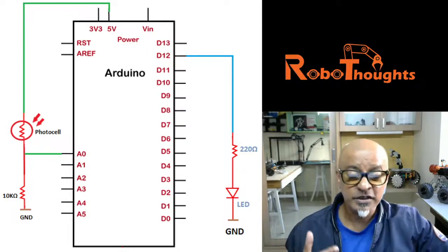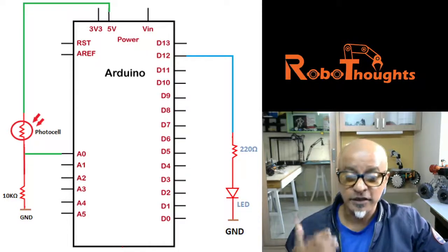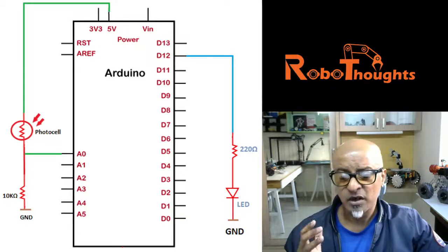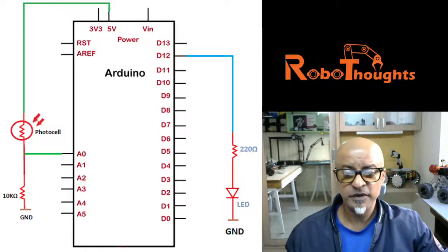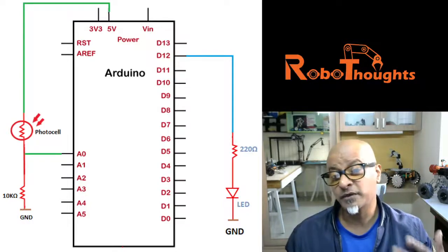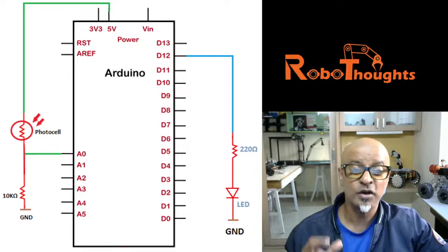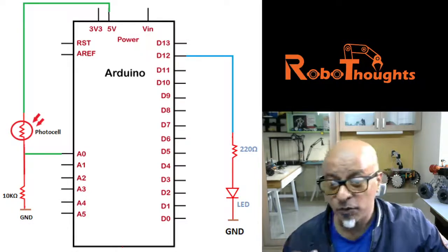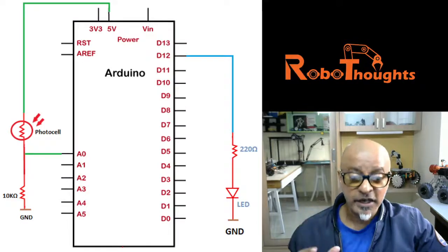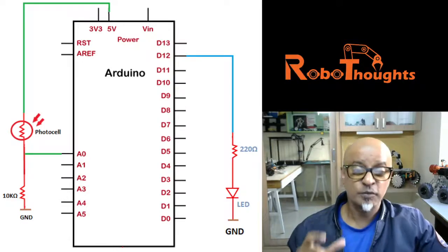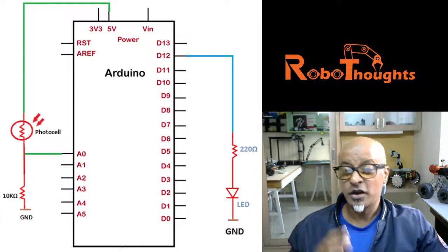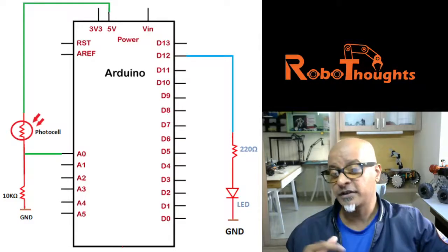So it means the resistance decreases as the intensity of the light increases. The resistance decreases with increasing light, hence the output voltage will automatically increase. It also means that the output voltage measured in the light will be higher than the output voltage measured in the dark. So that is how this LDR functions.